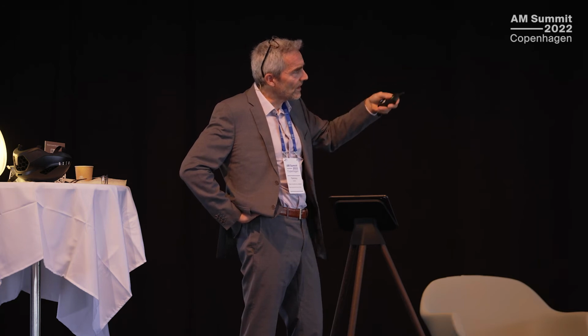And also you see this kind of soft shapes are really good because the early design is flat. So you have gathering of waste. And if you're bottling liquids like Coca-Cola, you have problems of corrosion. With that design, it was actually meant in a way so that the liquid doesn't stay on the part, so then you have a better life expectancy of the part.